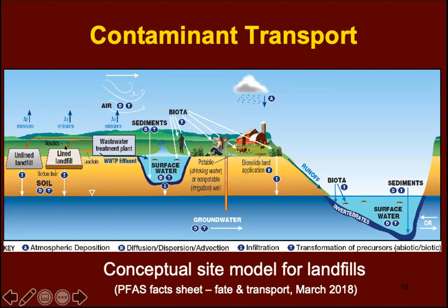Due to the decomposition of waste, you have arrows coming out from the landfill, where these gases are typically toxic, so they can contaminate the air. Another form is downwards through leakage, and this will result in the contamination of the soil beneath the landfill. If it reaches the groundwater, it will result in the contamination of the groundwater and probably the surface water eventually.